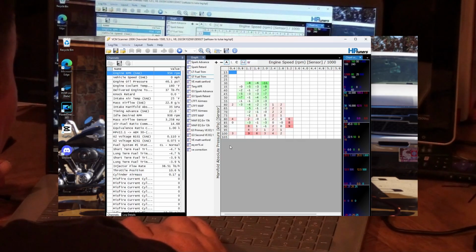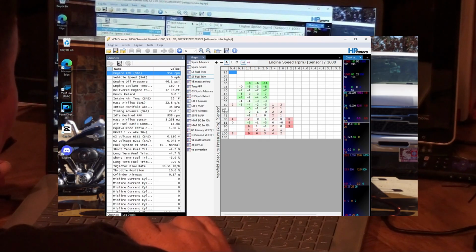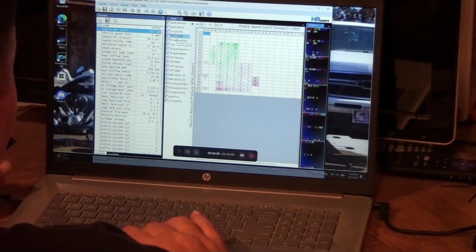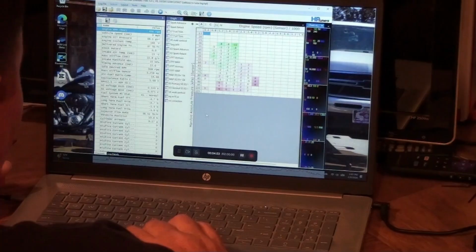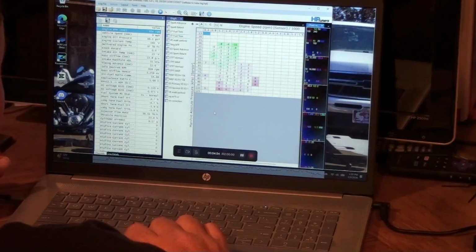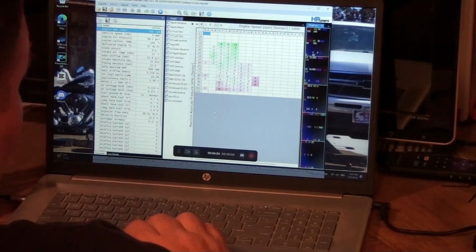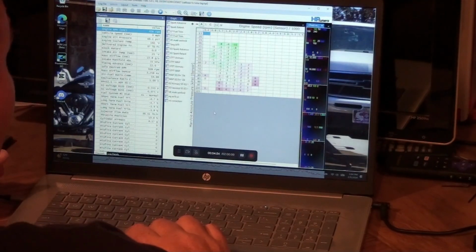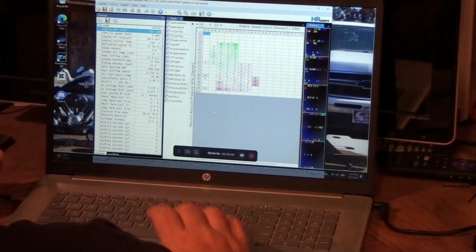We can see up here in our idling areas, okay, this is going to be controlled by our VE, and out here in our 2800 and up range is going to be our MAP section. And our long-term fuel trims plus our short-term fuel trims, divided by 100, plus 1, times the old value of whatever cell block you're working on and whatever chart you're doing, is going to be your math formula for how to correct your fuel trims.